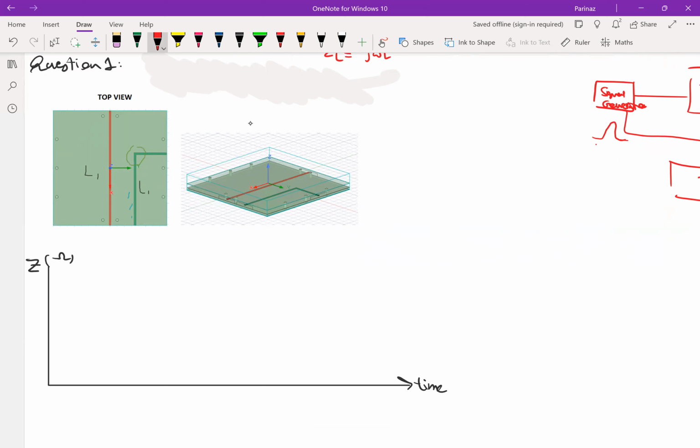The red one is going straight from a 50 ohm to a 50 ohm, and the widths and heights and everything about this line are designed so that this transmission line has a 50 ohm Z0 along the line. On the other hand, we have this green one. Again, it's launching from 50 ohm, going to 50 ohm, and the width, as you can see, is constant, but right here, it has a bend. So what is happening here?